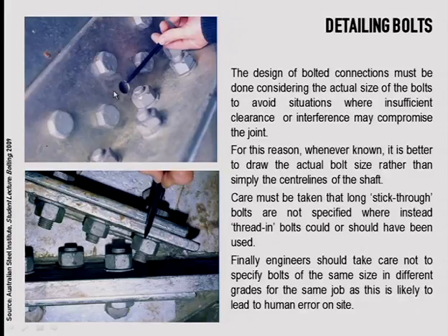one on the top, and other situations in which we cannot tie the bolt, such as this one in the bottom, you see here. So these are not secondary things, so it's very important that you are able to detail these things properly. So when you get these very sharp angles and connections, it's important that the detail is done properly, not to get in this type of troubles.